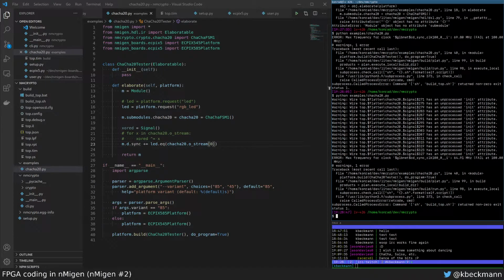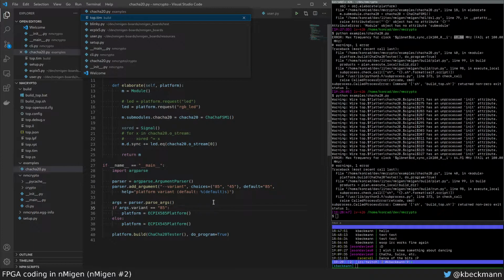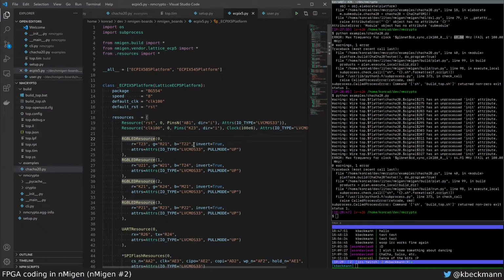Okay, it's because, right, okay. So I didn't really think. This platform runs at 100 megahertz, and the design is simply not that fast. So that's the issue. So what we could do is to change the frequency, because this is still just a synthetic test.